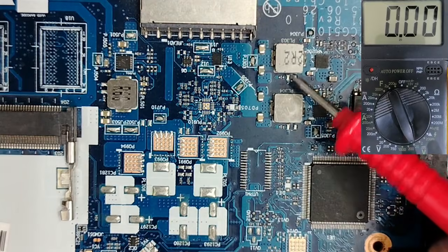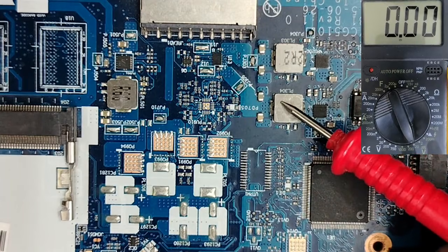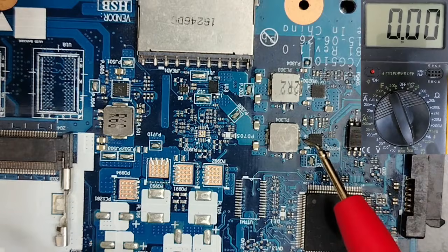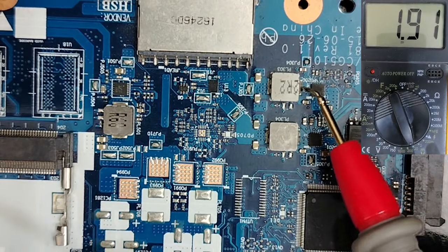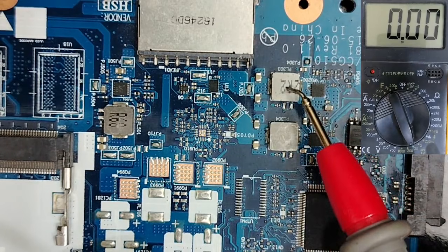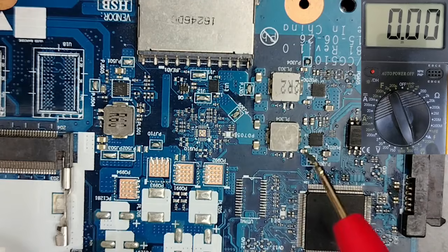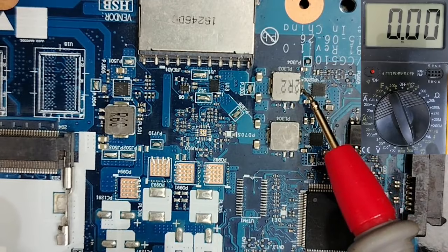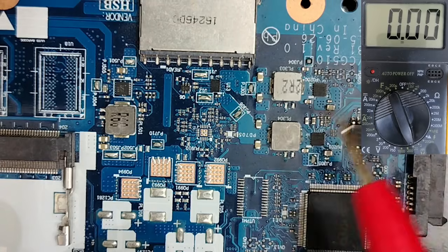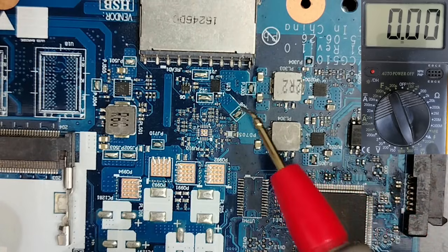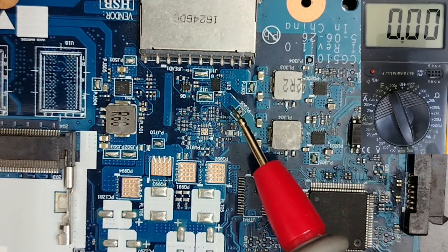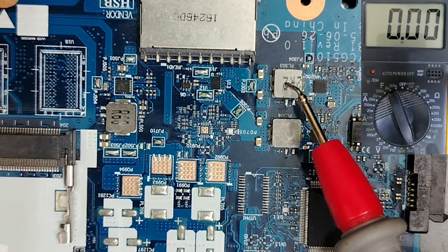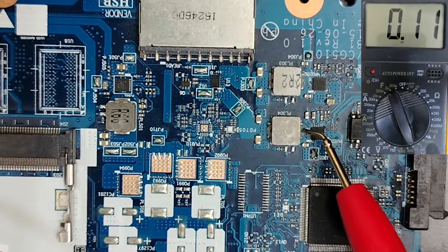So this is the 3V 5V circuit that we're going to study. Let's use the multimeter. Let's put the multimeter, as you can see, to 20 volts. Of course, if we check this inductor, we have 5 volt, and on this inductor we have 3 volt. This is very simple and very basic. But if you didn't find 5 volt and 3 volt here, maybe you will get stuck, especially beginners. You will not figure out where the problem is. Okay, so I'm going to teach you from the beginning how to trace the voltage from the beginning to the end in the 3V 5V circuit in order to fix it if you didn't find 3V and 5V.